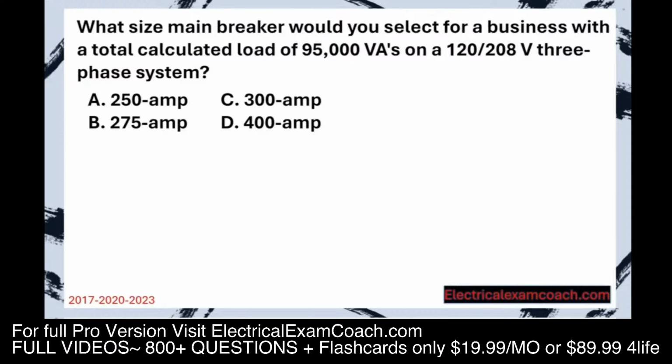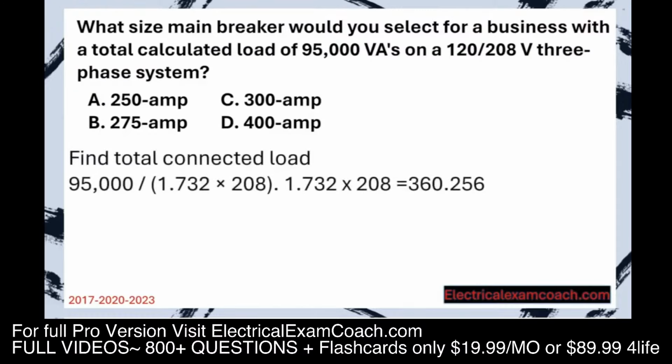120/208 three-phase system. Step 1, find our total connected load. Well, they've already given us our total VAs, so all we have to do is divide. But with three-phase, there's one extra step. Because of the geometric nature of three-phase, we have to take that 208 and multiply it by the square root of 3. The square root of 3 just so happens to be 1.732.